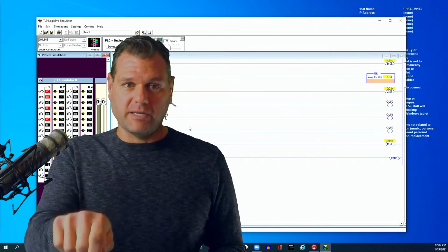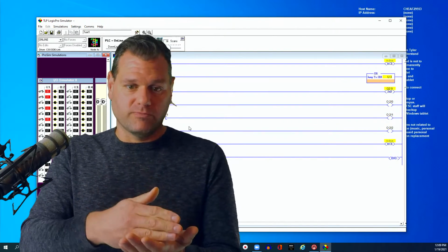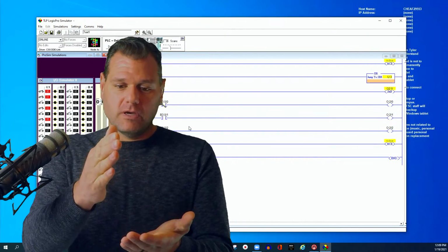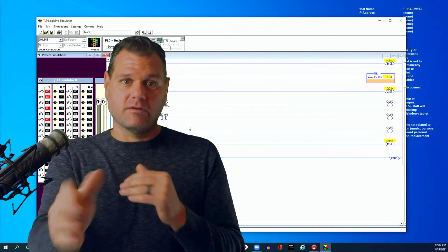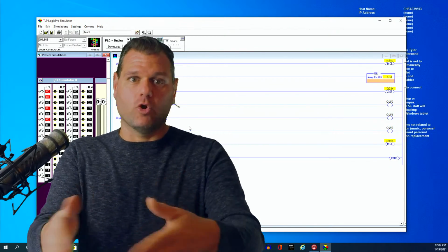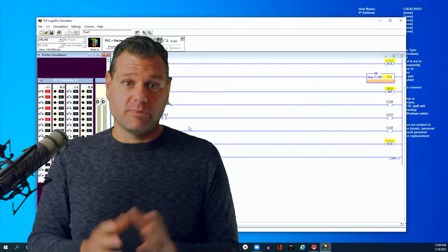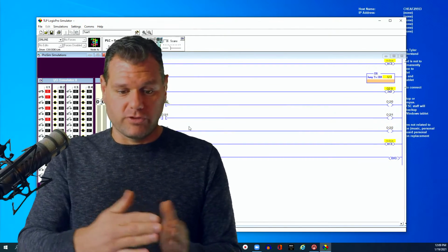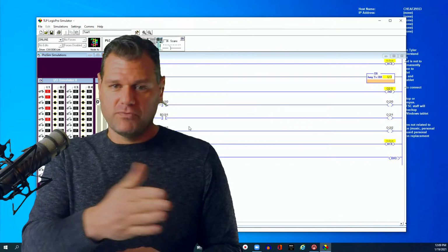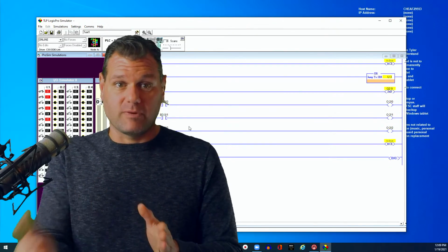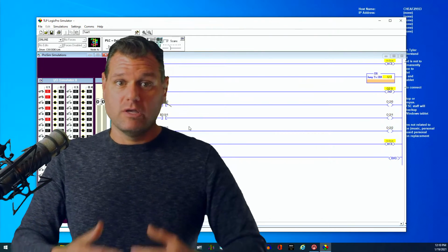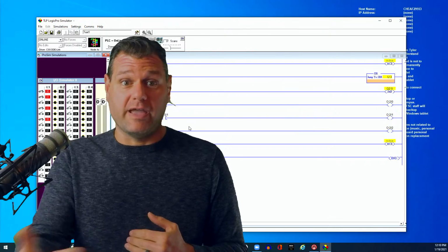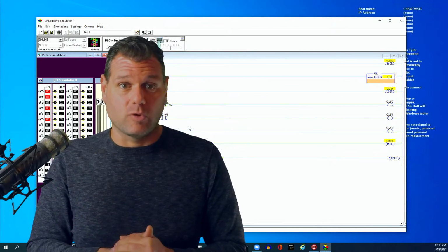So I would put in a maintenance key. I'd stick a key in and rotate it. It would set a mask in place, and the mask would say, okay, you are masking all the doors, so now you can walk over and open the doors, and the machine has no idea, because in the last state before the mask was in place, it saw the doors closed. Even though the switch is opened and it sees a 1 now, it doesn't know that. You completely masked it from its destination. So the machine is running as normal because you masked it from the destination. The destination would have been the error, which would have shut the machine down if it had happened normally.